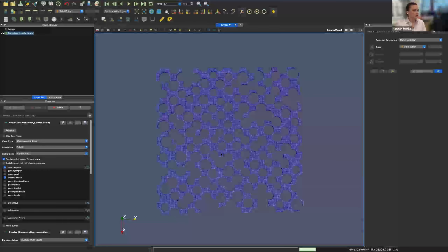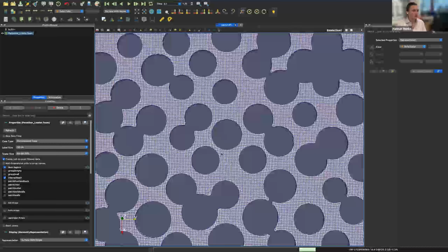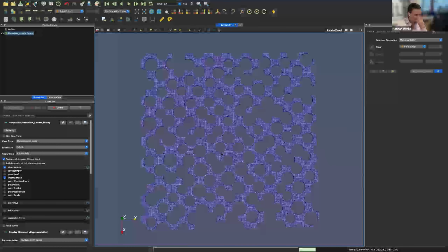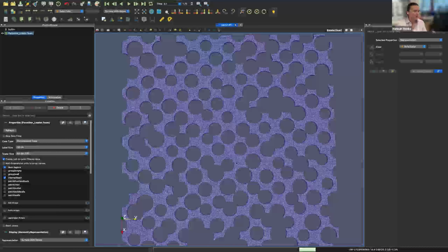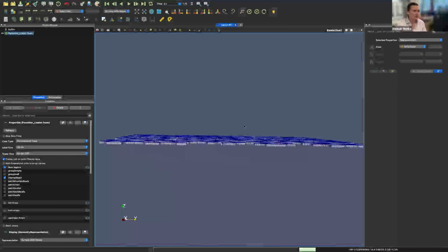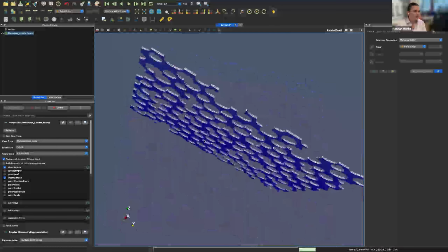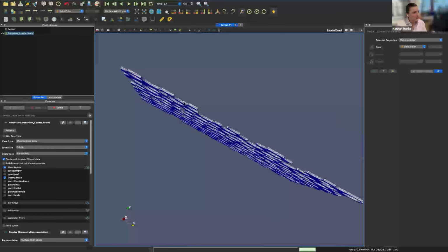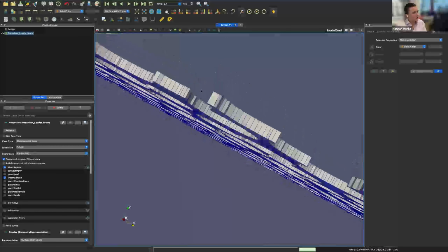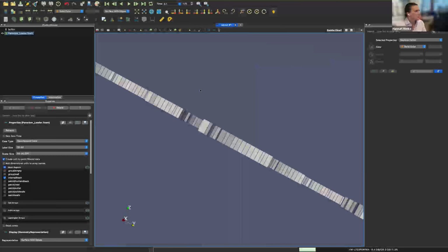So if we look at surface with edges, again, the mesh. Because you're only seeing, so we've essentially compounded the Z completely. So there's only one cell in the Z direction. And that's automatic in this tutorial. That's a 2D, essentially.